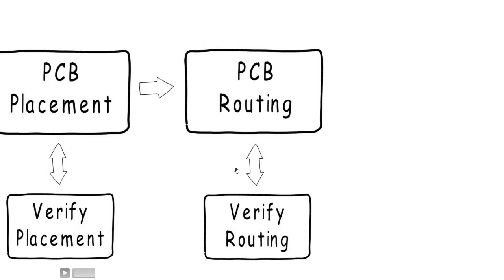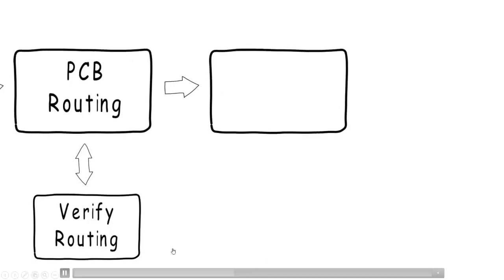You can segregate the rules into different groups and categories based on the process I'm using for the phase of the design that I'm at, and it makes the process of doing the DRCs much faster. We'll talk about that a little bit more in detail when I show a quick demo of the tool. So then we move on to final verification after verifying the routing.